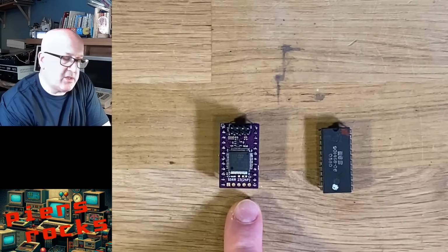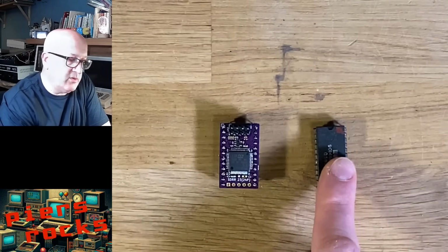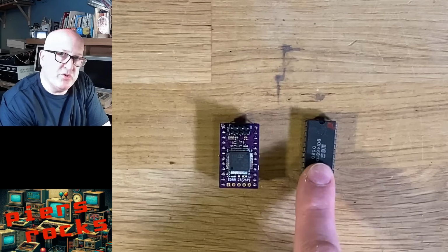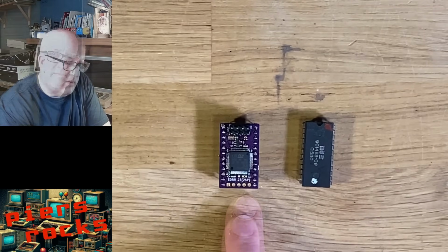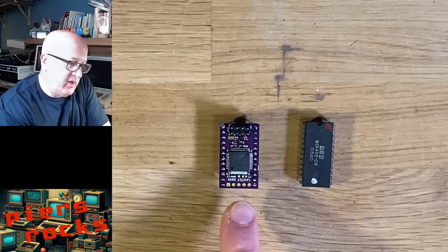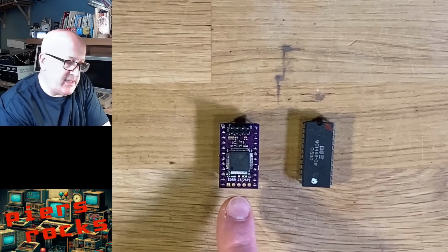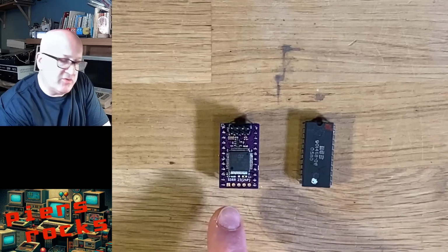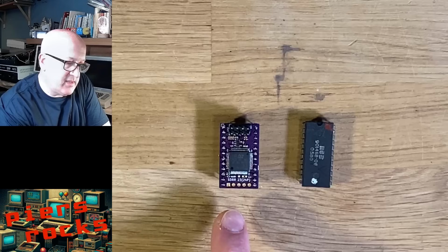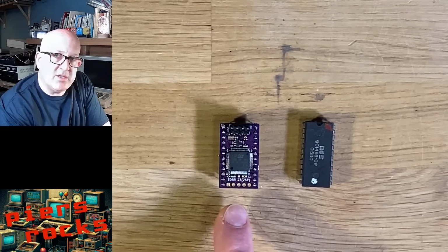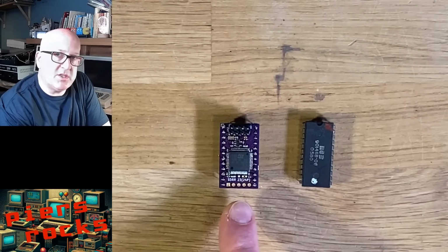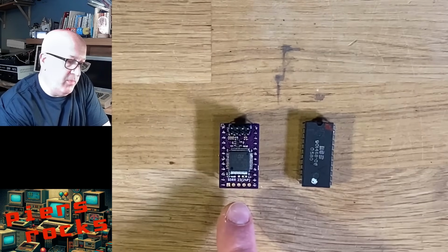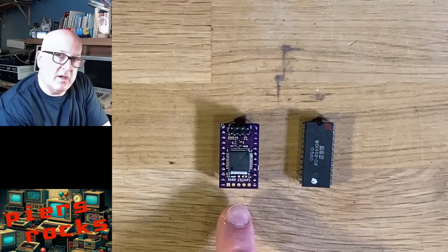I designed this to be as compact as possible, and it's very close to the footprint of the original ROM, and it's identical to the footprint of the original ROM sockets. This solution is pretty cost effective. It uses a $2 microcontroller from ST, a 10-cent voltage regulator, and then a handful of passives plus some header pins. The PCB is two-sided, and all the components are on one side of the PCB, so it's much cheaper to have the board manufactured than a more complex design.